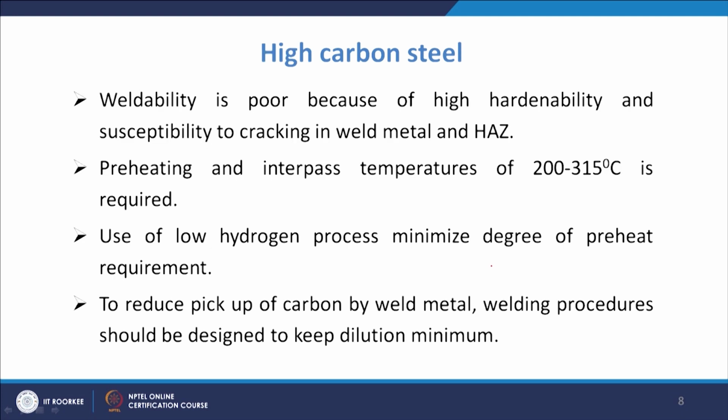Coming to the high carbon steel. As we discussed, the welding of high carbon steels is a great challenge. Since the hardenability is increasing in high carbon steel, the weldability is considered to be poor, and there is a great chance of cracking in the weld metal or HAZ if proper precautions are not taken.